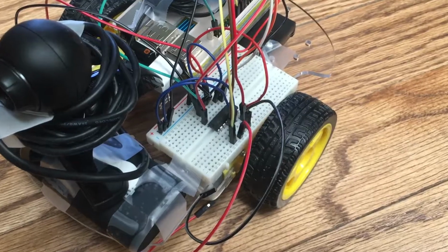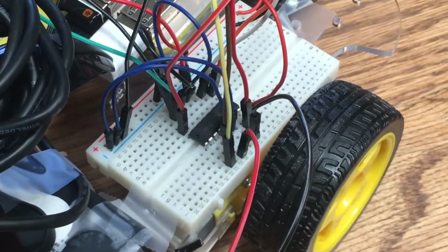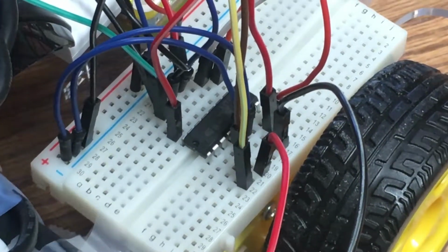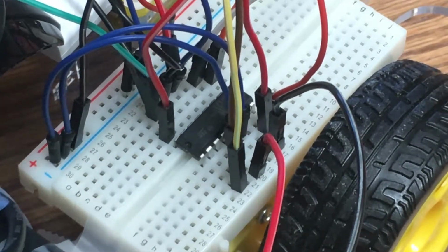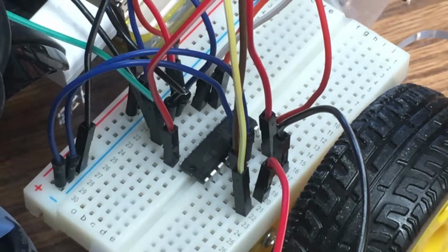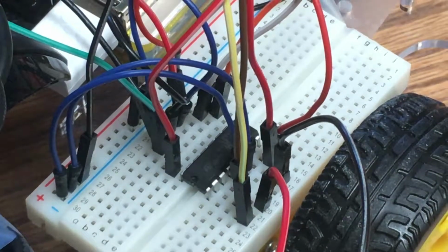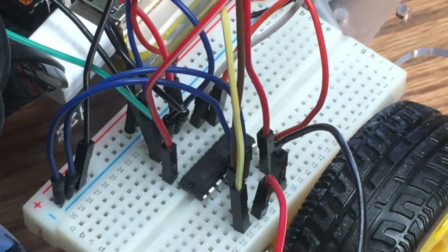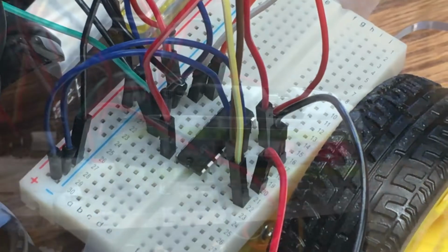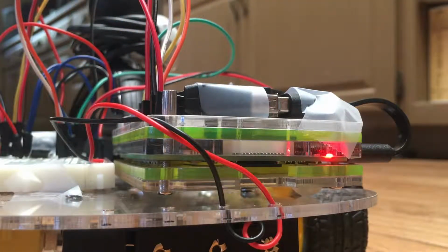The motors are more advanced in their wiring, and they must be connected to a set of 6 GPIO pins. To do this, a 16-pin chip called the L293D is placed on a breadboard, so all inputs and outputs go where they need to. 4 AA batteries provide power to the motors, while the 6 GPIO pins decide whether the motors receive that power. The Raspberry Pi also provides a 5-volt input and a ground for the circuit with 2 extra wires.